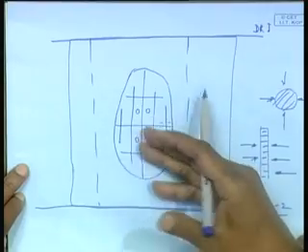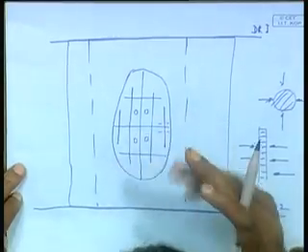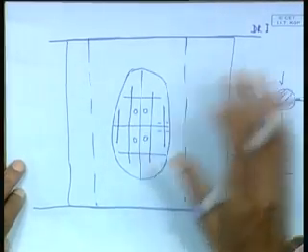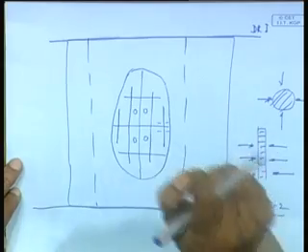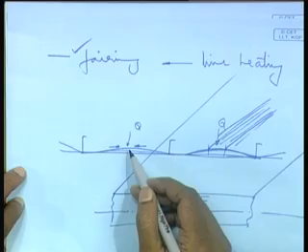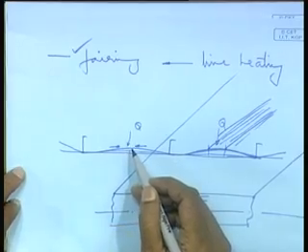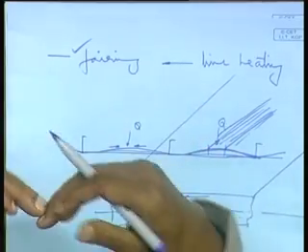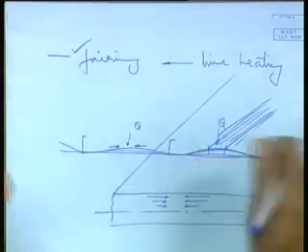But obviously that is not a good practice, because this is quite a lot of work, purely manual work and also skill based. One will know how much to heat and where to heat, etc. A simple thumb rule is heat on the convex side, obviously, because I want to shrink. On the convex side it has elongated, so I want to shrink. So heating on the convex side, that is fairing.